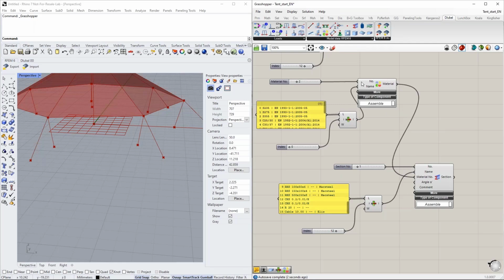So this S235 will be linked to this cross-section, but it's only working because I assigned the index number beforehand. This line basically transfers only the index number. This is what the component requires. So if you do not assign index numbers, you cannot follow this logic.